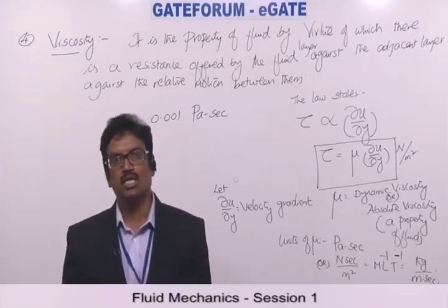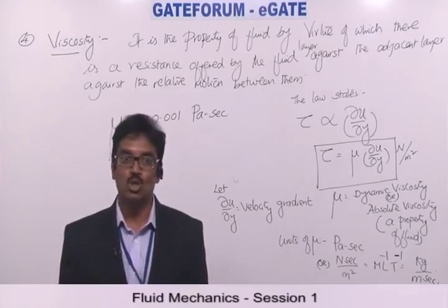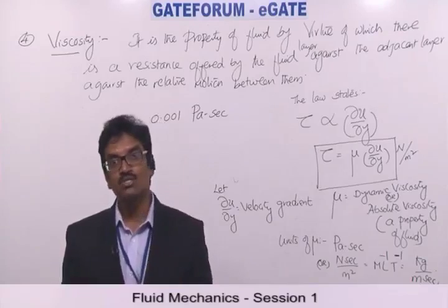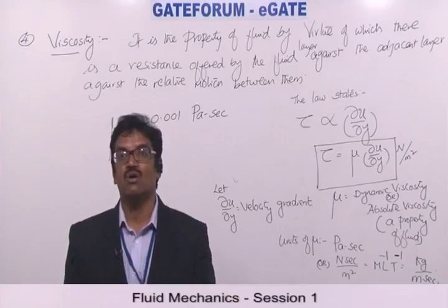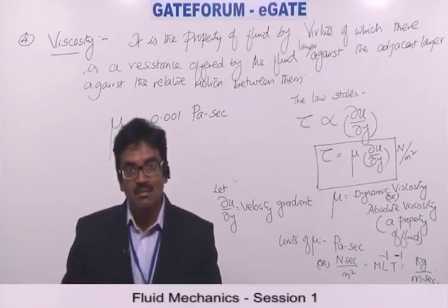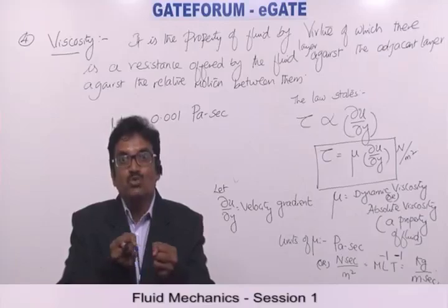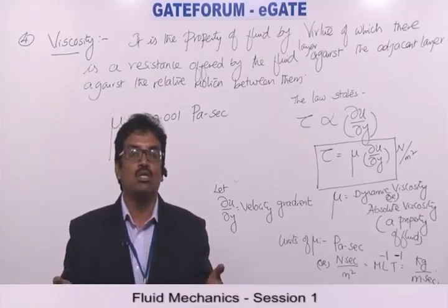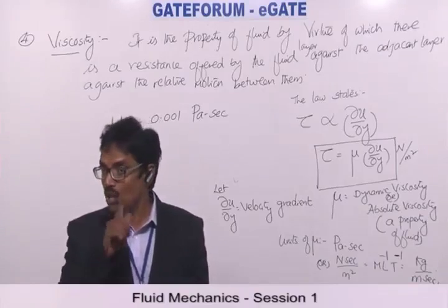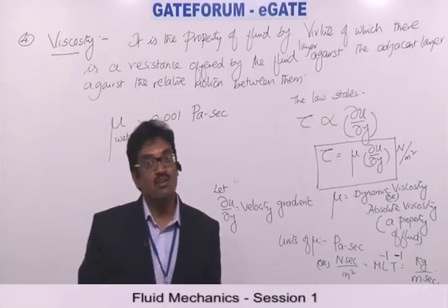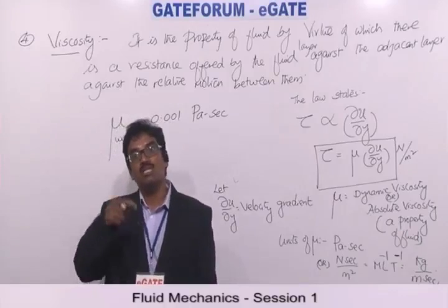There will be molecules in any fluid. There will be intermolecular attractive forces, which are also called cohesive forces. This viscosity in liquids is majorly because of the intermolecular attractive forces called cohesive forces. As the temperature of the liquid increases, the intermolecular cohesive forces get loosened, become weaker, therefore the viscosity decreases with increase of temperature. But when you come to gases, the viscosity is because of some other reason. The viscosity in gases is because of basically molecular momentum transfer.